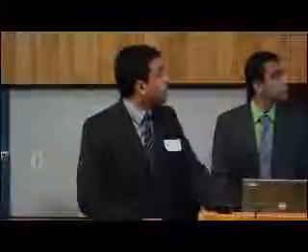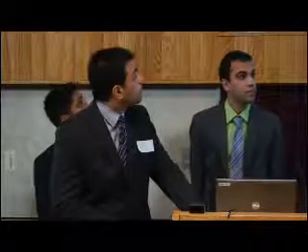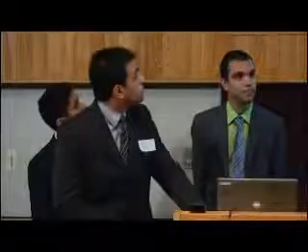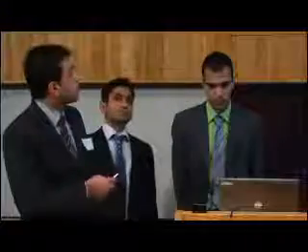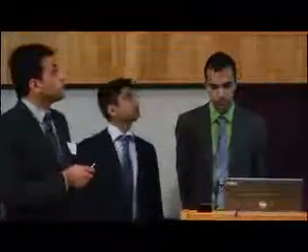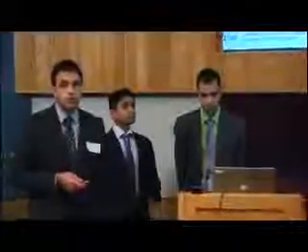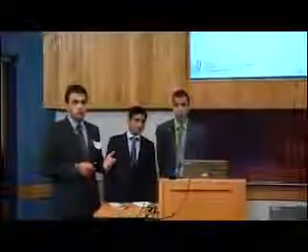The type of SCR reactor that we have in the process, as I can show here, is a high dust SCR reactor. By high dust, I mean it's before the electrostatic precipitator, which removes the dust particles. So there would be a chance of blocking in the SCR reactor.